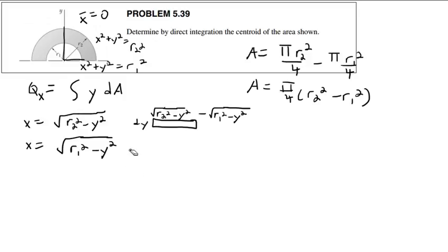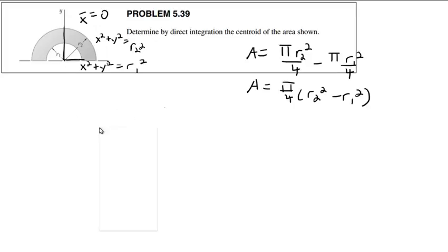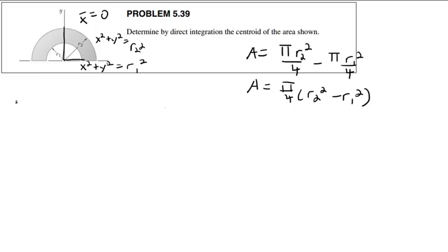Is there any way you can express your centroid coordinates as r theta? Yes, you can. What I'm going to do is break this into two pieces. I'm going to find the centroid of the inner piece and the outer piece and then combine them. So, inner piece centroid.